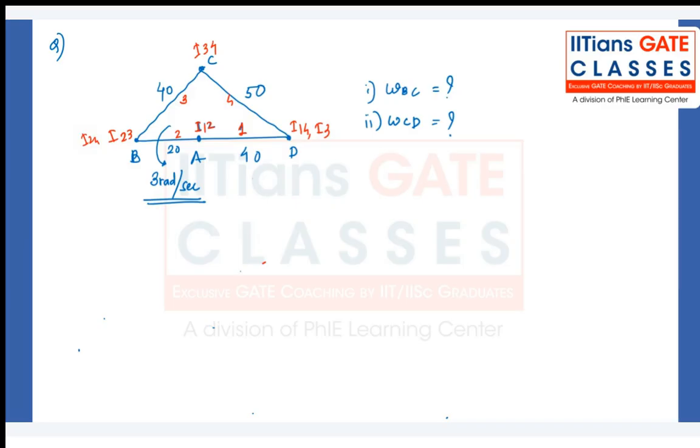That is making it easier to solve this problem by using I center method, because point B is already on the same line of AD. That's why it is I center for the link 2 and 4 as well. So that's why I'm solving this by using I center method.